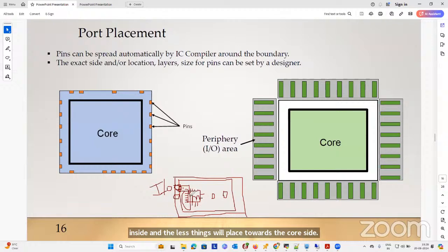Based on the number of pins or the density of the pins for each standard cell or macro, when we click on it in the tool, it will give the connectivities. Based on the connectivities, we have to move the direction of the pins or align the macros. Clear?